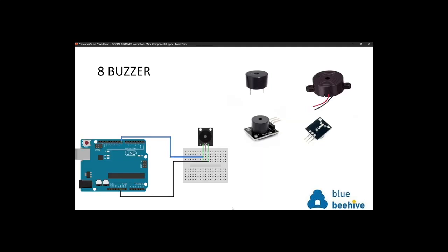The buzzer: we know there are many different kinds. I don't know which one you will have for developing, but the easiest is one with two pins, one for the positive side and the other for the negative. Normally the positive will be connected to a port of the Arduino so that we can control the sound that we want to launch. Whatever you want to use, with two or three pins, don't mind, because in the end we will use it the same way.